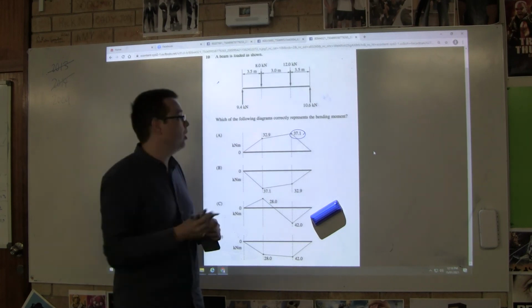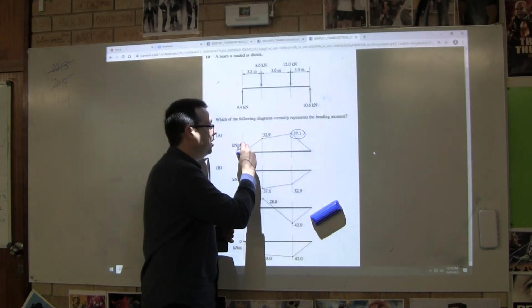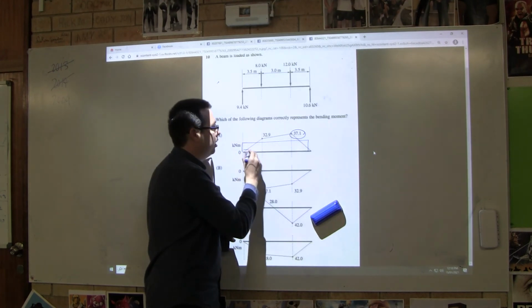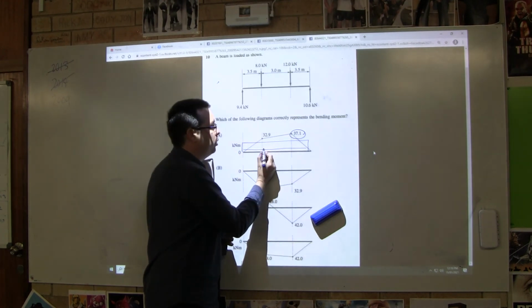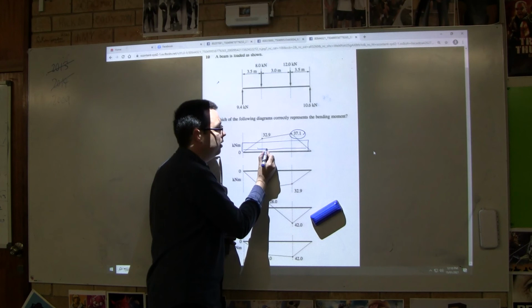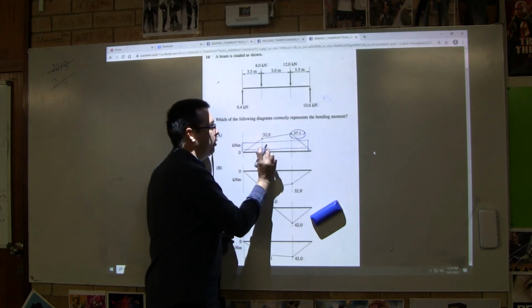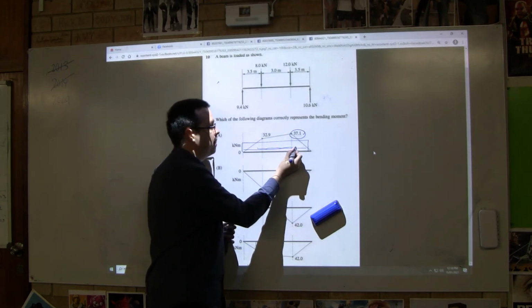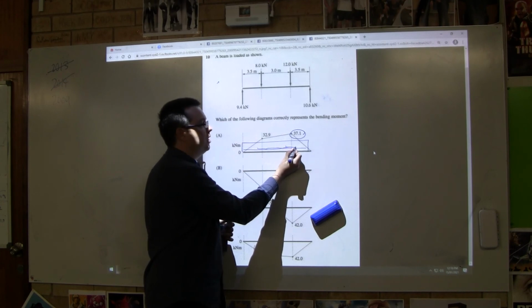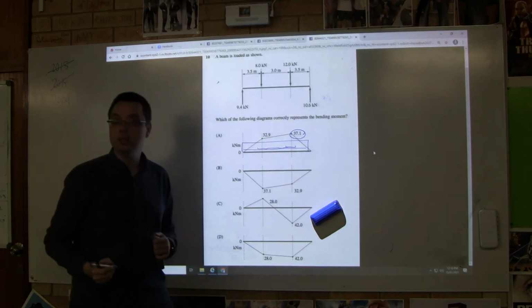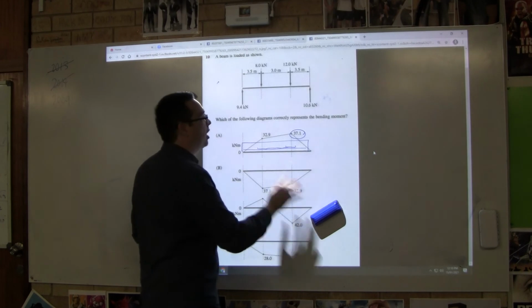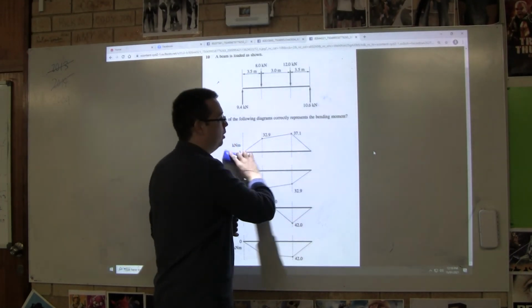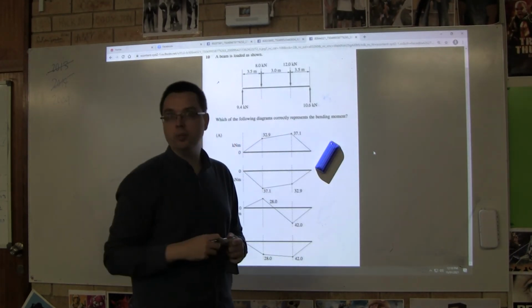But as we talked about earlier, if we were putting steel in this beam, we might put a little bit of steel the whole way, and then add some more steel here, and then add the most steel there. Does that make sense? We could add more and more steel. If you're putting a steel beam in, you probably just use the beam that suits the biggest moment.